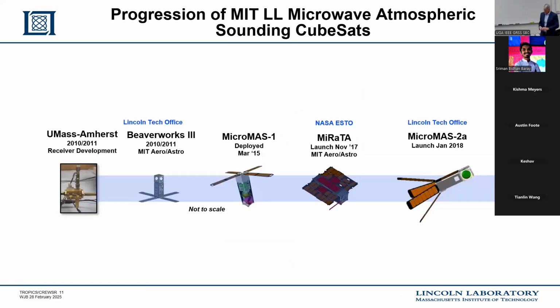Okay, so on the technology side, we've been working for over a decade to try to miniaturize the sensor. Remember the satellite I showed you earlier fits in this room, and the instrument is about the size of this desk, right? So we asked the question, what would it take to make that smaller? And the laws of physics dictate that you need the antenna size to resolve the eye of the hurricane. It turns out that aperture is about the size, maybe 10 centimeters. It's not that big. Most of the instrument is electronics, which we can miniaturize.